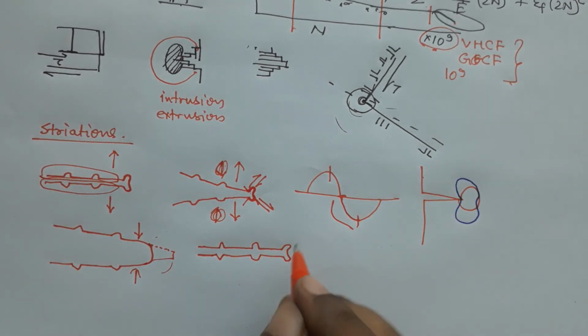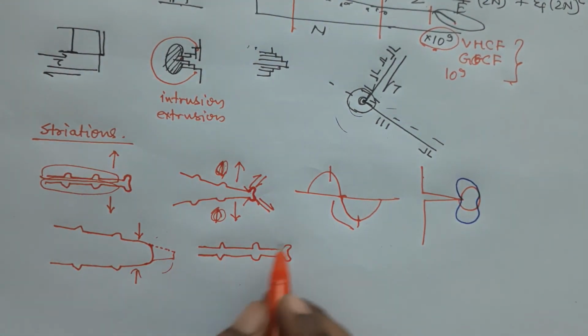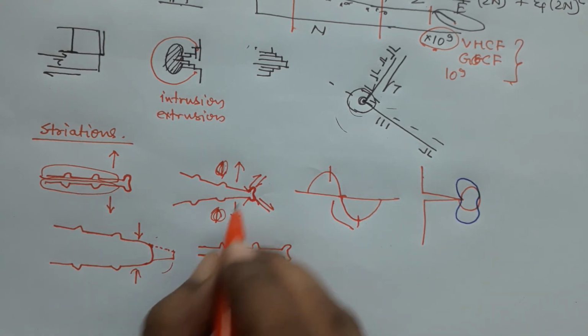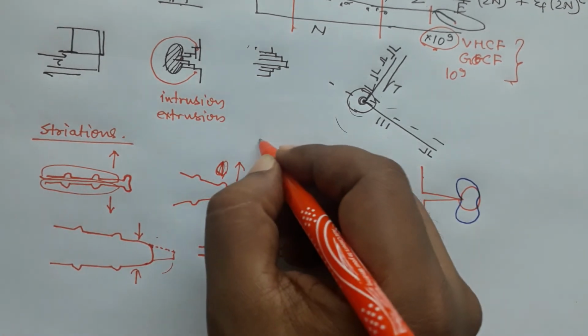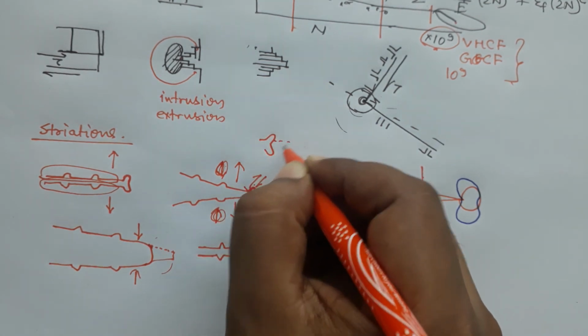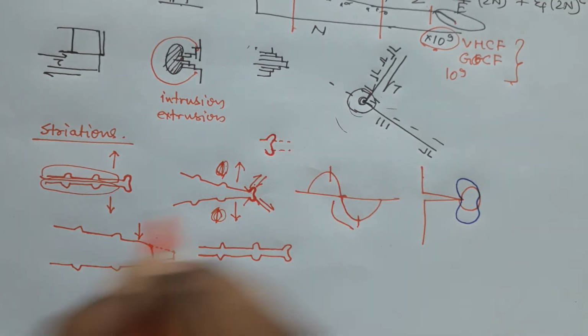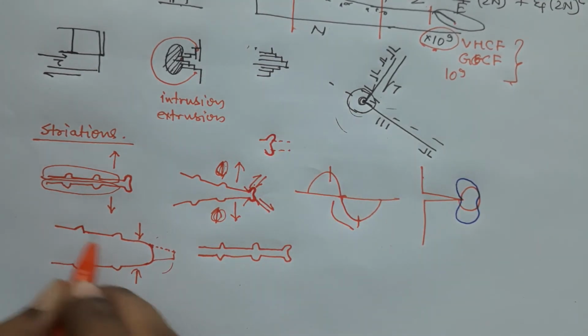It gets closed, and then the same thing is repeated over and over again, and because of this damage the crack can propagate. Because of this shear band, the crack takes this kind of form, then it propagates and this part is left there, and this is why you see these parts.